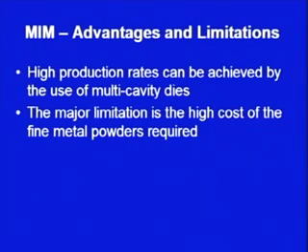Then the major limitation is the high cost of the fine metal powders required. So, the size of the powder required here is very fine. So, fine powders will add to the cost of the process. So, the major limitation of metal injection molding is that the cost of metal powders required for this process is comparatively high. The other compaction processes are rolling.